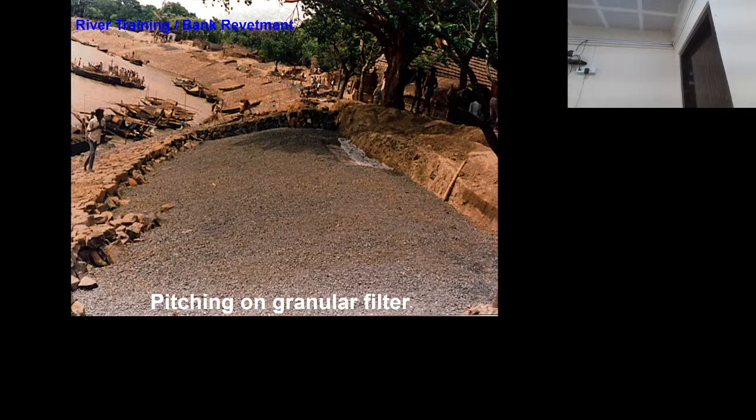Suppose this is the original soil. Before placing the geosynthetic material in the protection works, we have to fill 30 centimeter of sand.